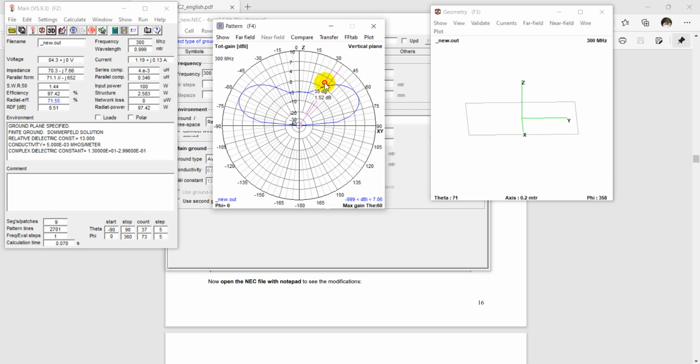If you rotate this to the other side, then you can see at minus 60 degrees the gain is maximum, and in the other range the total value is 0, and the cursor does not move to the negative portion of this z-axis, which means the antenna cannot radiate underground or at ground level. It can radiate above the ground level, and the maximum radiation happens at 60 degrees.